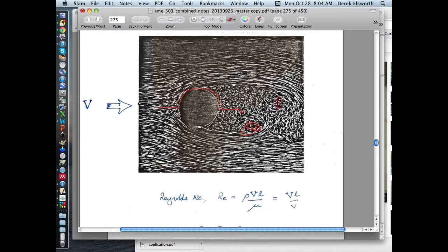As you increase the velocities to larger ones, you'll get this regime where you have these eddies which are shed off. I'm not sure which ways these would be circulating. You can see an eddy there, and you can see an eddy there. And so at any particular flow regime, which is indexed by a certain number, it would look different from the flow regime at a different velocity. And the index that we use to identify typically kinematic similitude, in other words, the kinematics of flow, the geometry or topology, morphology of flow is the same, is typically the Reynolds number. And so that's the second thing that we look for.